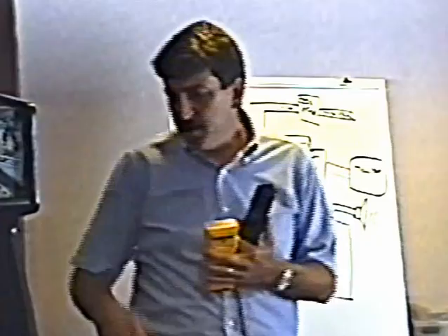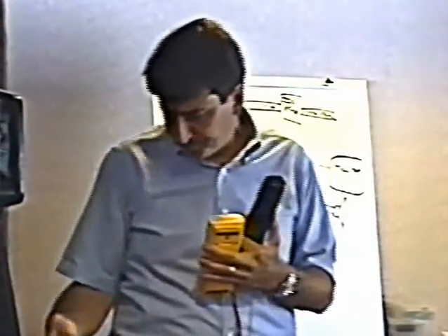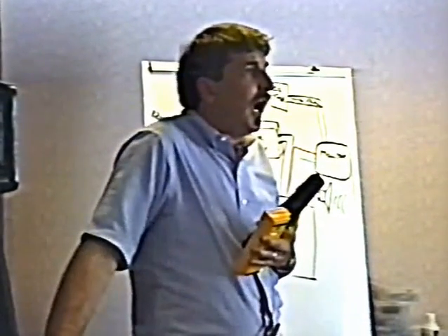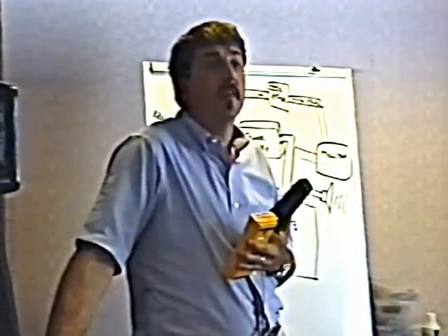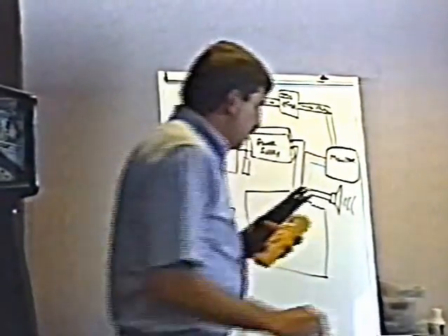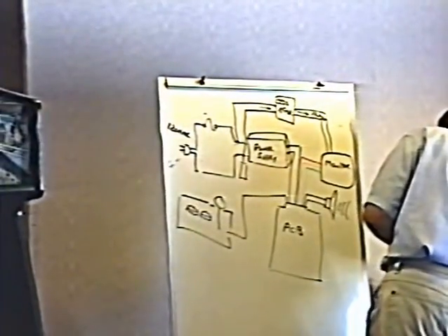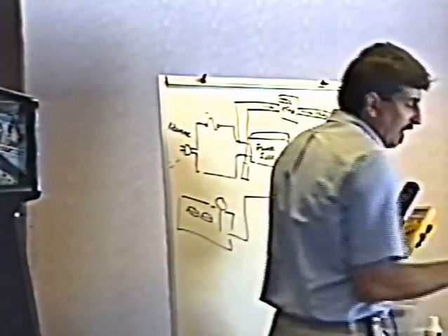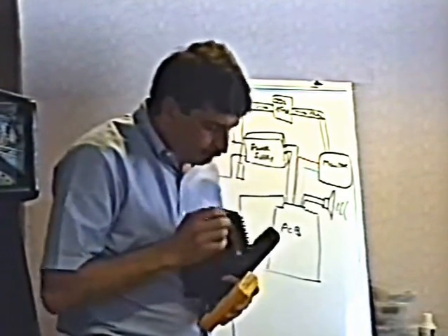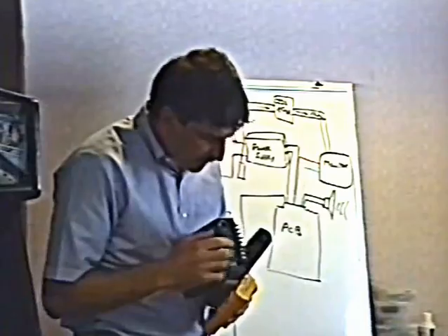So let's say you coin up the game and you don't hear any game sounds whatsoever. The next thing you want to do is check the power supply. Check to see if you have your 5 volts. Now, certainly, if you just want to check the power supply to see if it's working or not, that's pretty simple. On the power supply, you've got the screws on the side. In fact, let me go over here and show you up close what I'm talking about.